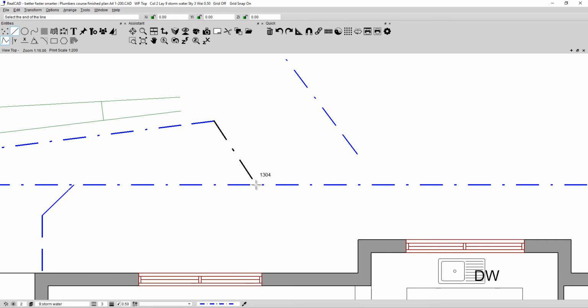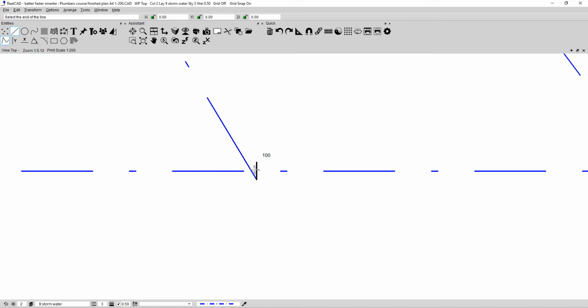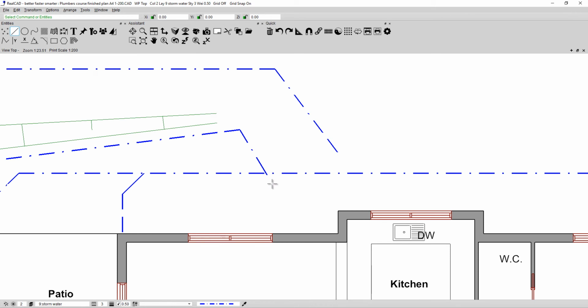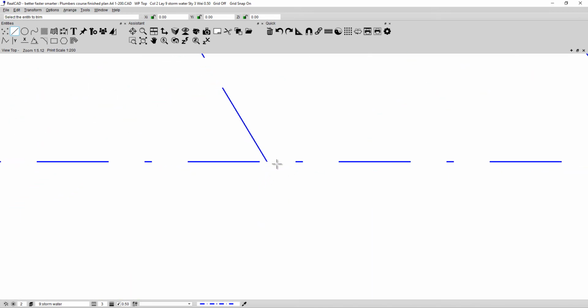Again, hold down the control key, and I actually want there to be it. Well, that would appear to be where there is a snapping point. So I'd say that this blue line isn't actually snapped to a grid point, or it's 100 mils away from where I've just clicked. How do I fix it? Right click, trim to here. So now I feel much more comfortable that that's directly in a line.